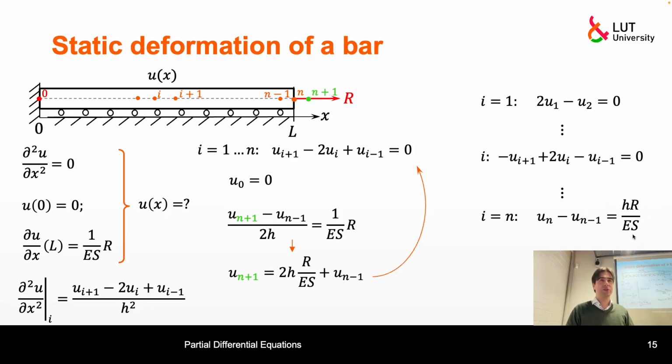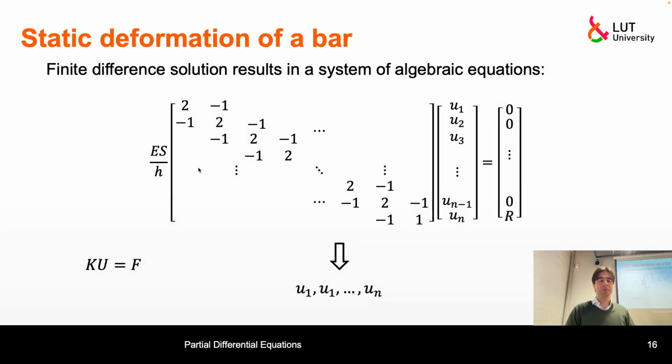It had this force in the right hand side with certain multipliers, but I put them in front of this left hand side to make it consistent with what you will get in finite elements naturally, and what you would get if you considered a more general problem, like having body forces applied to this problem. And this is what I will encourage you to do in your first part of the assignment.